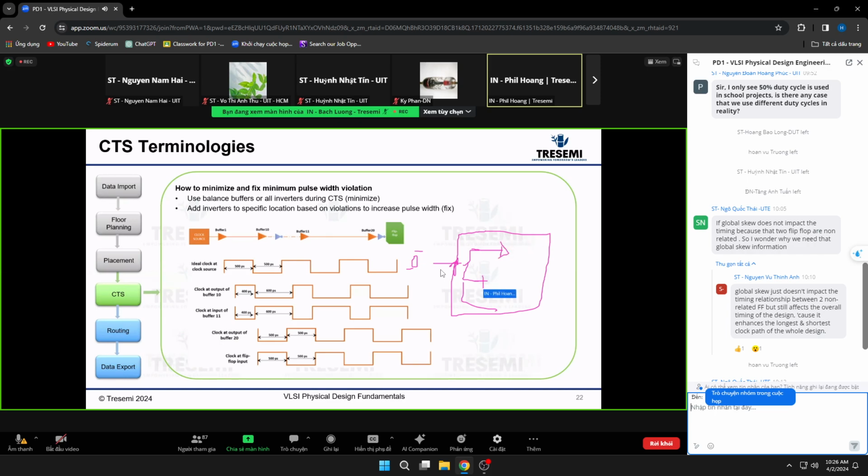a different buffer, for example, and you can create a clock at the output of these three. You can have clock 1, 2, and 3 either at the same frequency or different frequencies, and then each of these three are independently synchronized to each other, meaning that you have clock skew groups.